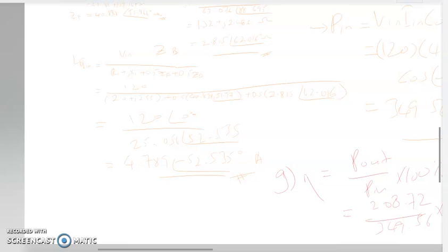Okay, let's say we have here the load angle. So this is your NS, synchronous speed. This is your mechanical speed. So it crosses here, so this is your load profile. This is your load torque. And at this synchronous speed, for sure there's no torque. So the load torque happens here.